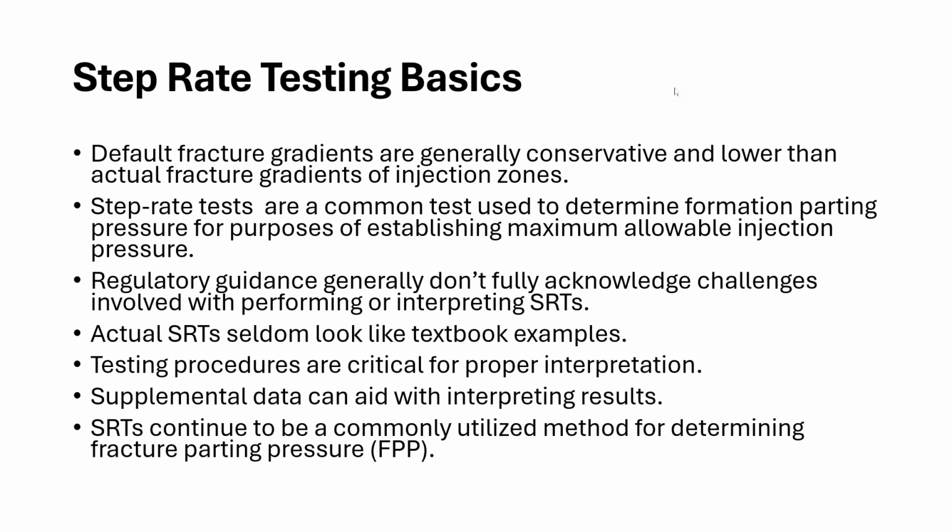Regulatory guidance generally doesn't acknowledge the challenges involved with performing or interpreting step rate tests. We have seen in so many cases that actual step rate tests seldom look like the examples they put into the textbook. So with that in mind, testing procedures are critical, and you have to have a proper interpretation and a thorough analysis of the data you receive. Supplemental data can aid with interpreting those results, and we're going to get into some of those methods that we can use to supplement a report and analysis.